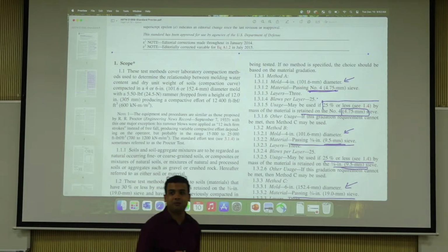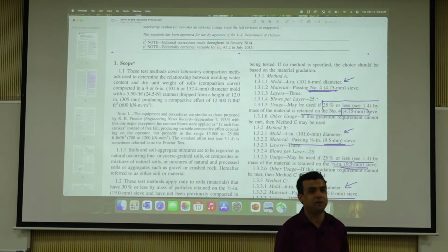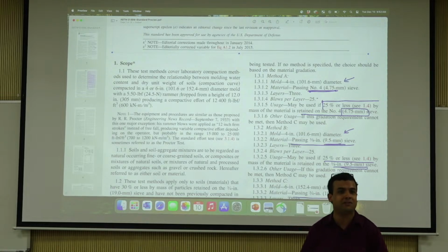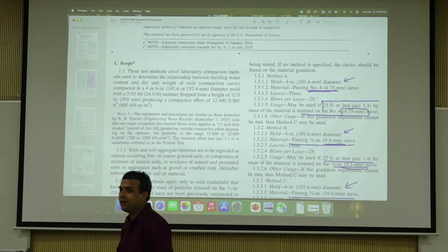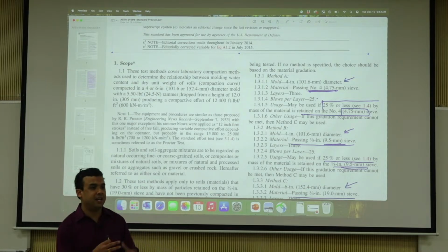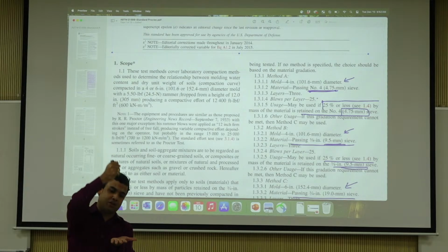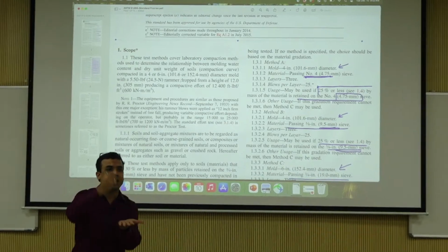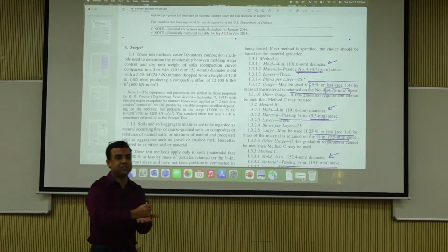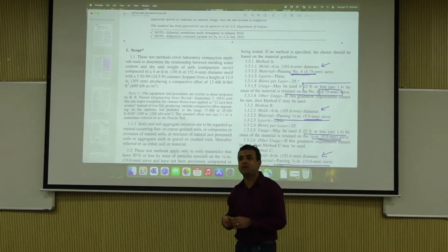So what I'm trying to say is when you do an engineering document, do not write it as a standard Proctor test, because you are not doing a standard Proctor test. Nobody is doing it, right? So Proctor, when he developed the test, he developed it for sandy soils, and it was firm blows. So what it means is that you take the hammer, you actually bring it down, and you use your hand to do this. It was not a free fall. It is not just mgh as the energy. So there is a lot of variation in that. So it was actually modified into that.